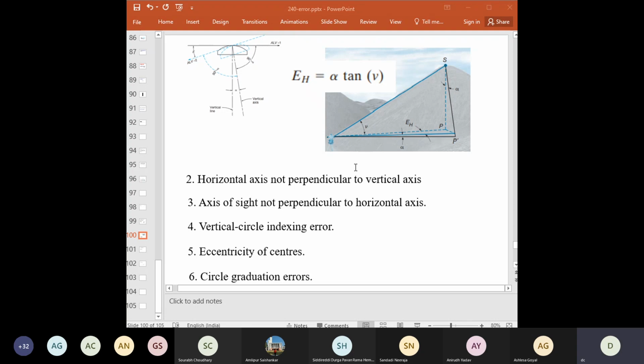In flat terrain, this is approximately the cause of error due to improper level, so a misleveled setup, but it can be small. However, in mountainous terrain where the backsight and foresight points can vary by large amounts, this error can become substantial.